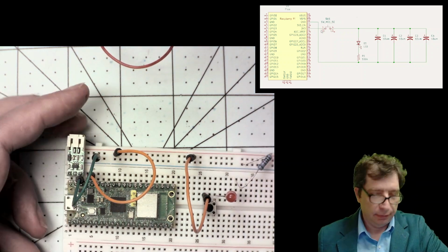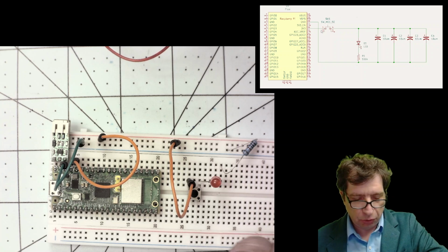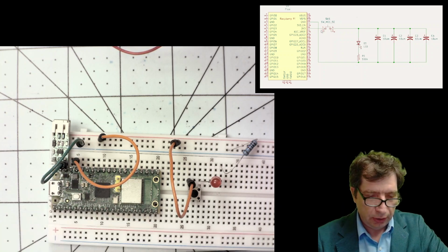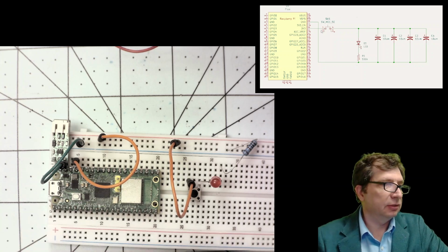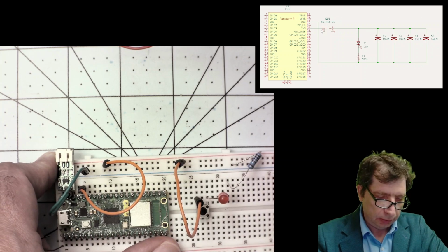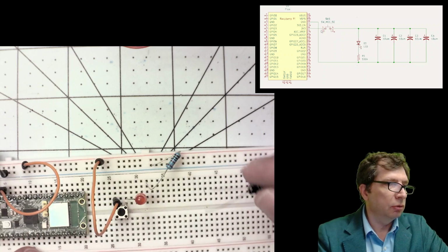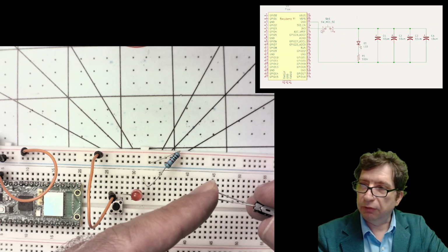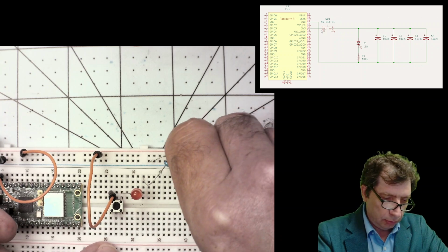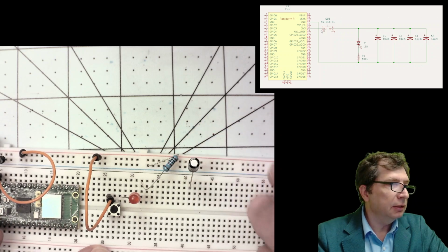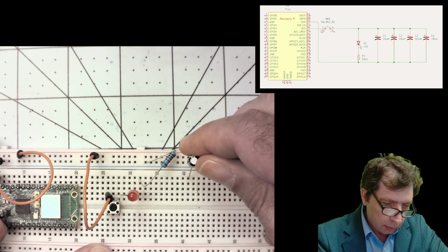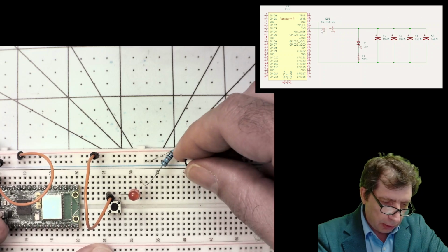and keep adding. I suggest to use 4 capacitors. I'm going to show you only 2 of them, but the work is the same. So I am plugging capacitors into the board. The short leg of the capacitor is negative, goes to the ground, and I'm plugging it like this. We can do it, okay.